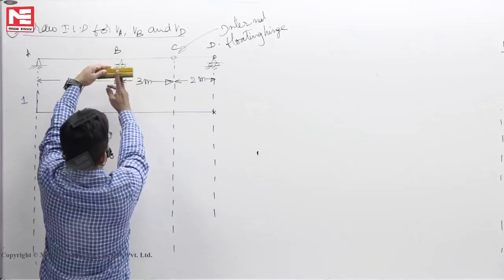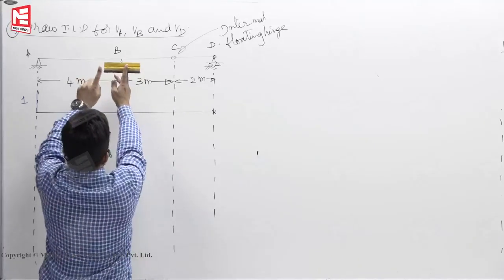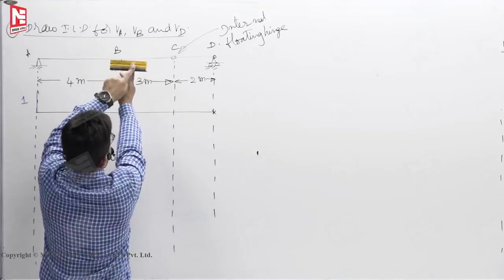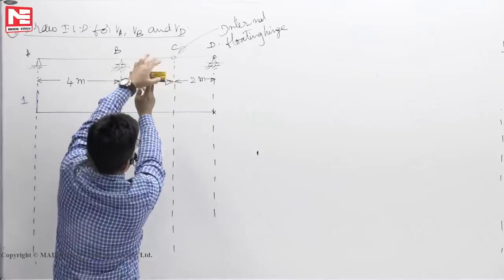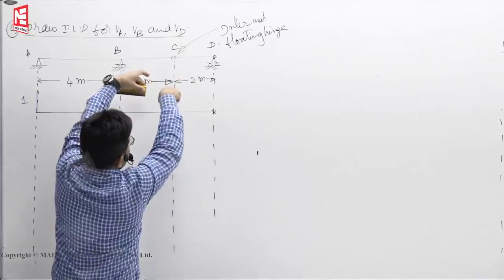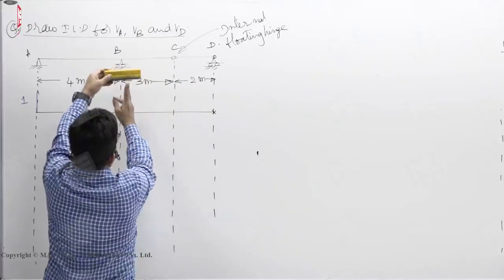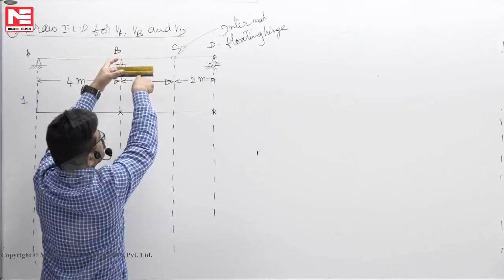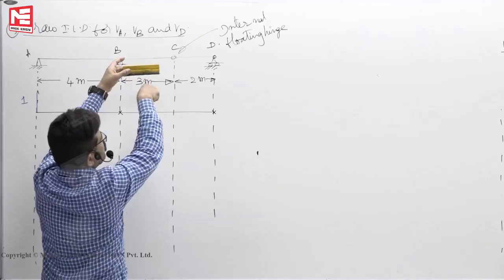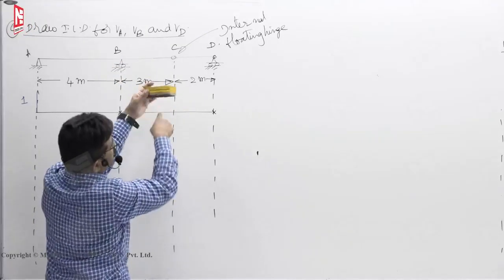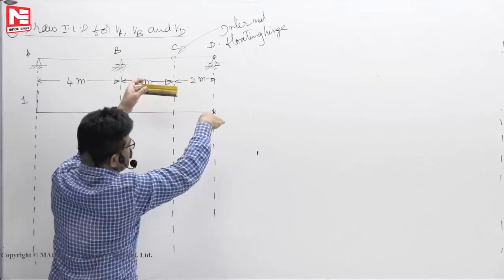This point where I am holding is B, say. This point is A. This point is C. A, B, C is a single beam. At C, the CD member, another member, is connected here and it is free to come up and down. So at B, actually a single beam, roller is here like this. If a gap is there like this, then you have to weld a triangular plate here. Here also you have to weld a triangular plate. One base plate you have to weld.